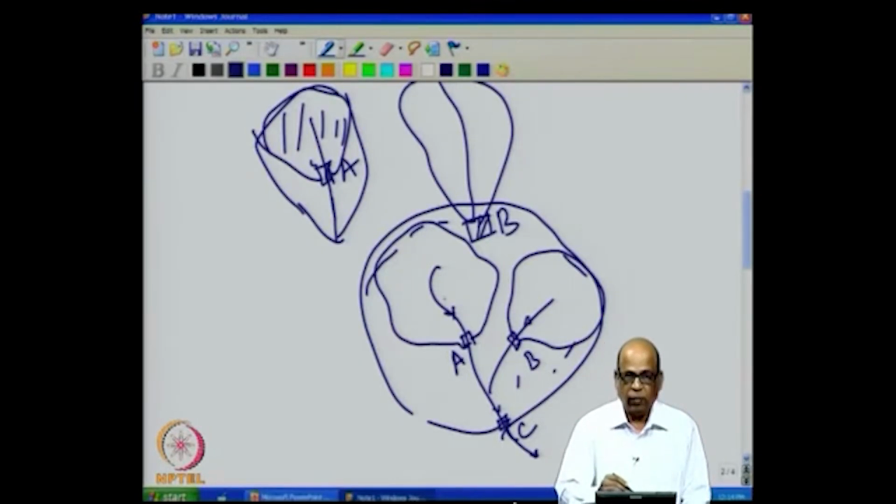The areas are different and so are the flows at all of these locations, but the ratio of the flows to the areas will be approximately the same if they are hydrologically homogeneous, which means that the precipitation pattern is the same in all the three catchments, as well as the land use patterns, the vegetation, the amount of urbanization, and the type of soils.